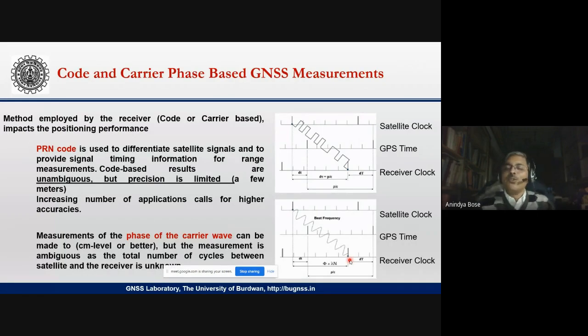But now I'm giving you a smaller scale, say a 30 centimeter scale, what we use in our day-to-day life for drawing lines. So now if you measure the same length using the smaller scale, obviously you can very well understand it's very difficult. You have to measure it multiple times. But instead of 3.3 meters, it will tell you it is not 3.3 meters. It is 3.311 meter or 3.31 meter. So you can very well understand we are getting one order of better measurement. But in the second case, the process is cumbersome and there may be errors.